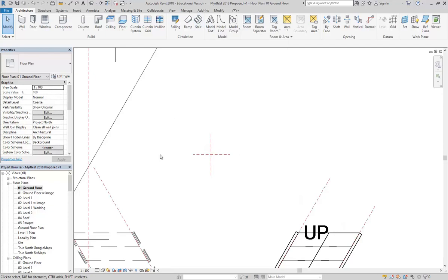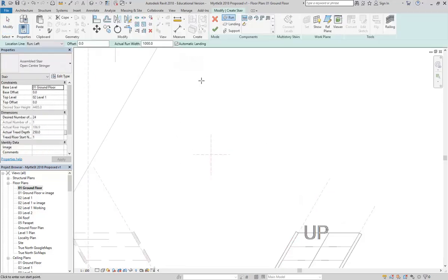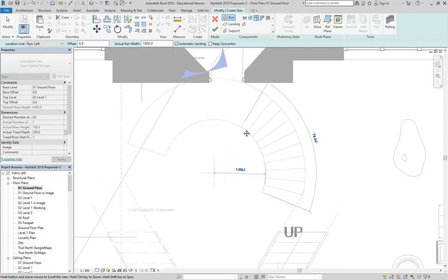It won't just be the stairs. Think about what else you'll need to make. You'll have voids and floors and all sorts of things that need to have the same centre point because they're going to follow the same curve. So it's really helpful to mark it out, and then if I go to make a stair, I can again choose centre end spiral, start on that centre point because you always have to give the centre point, and I can come out and give the first step, and then come around and count to 18.